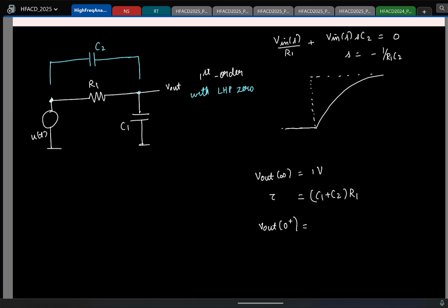Why can't it flow? This is a voltage source. What he's saying is if the voltage across the capacitor has to have a step jump, the current through the capacitor must be an impulse. So why can't this impulse current flow in this network? This is a voltage source, you can provide any current. What is limiting the impulse current from flowing in the network? He's saying this current has to flow through the resistor. So what?